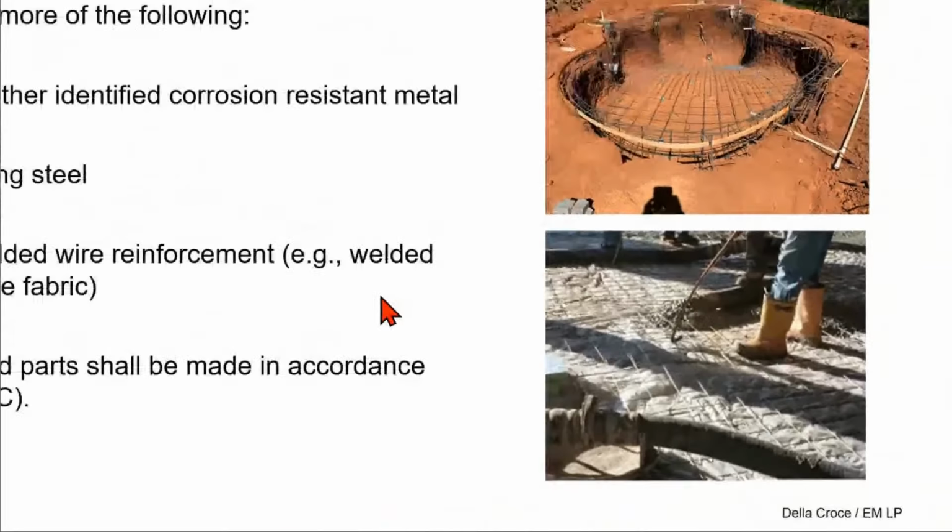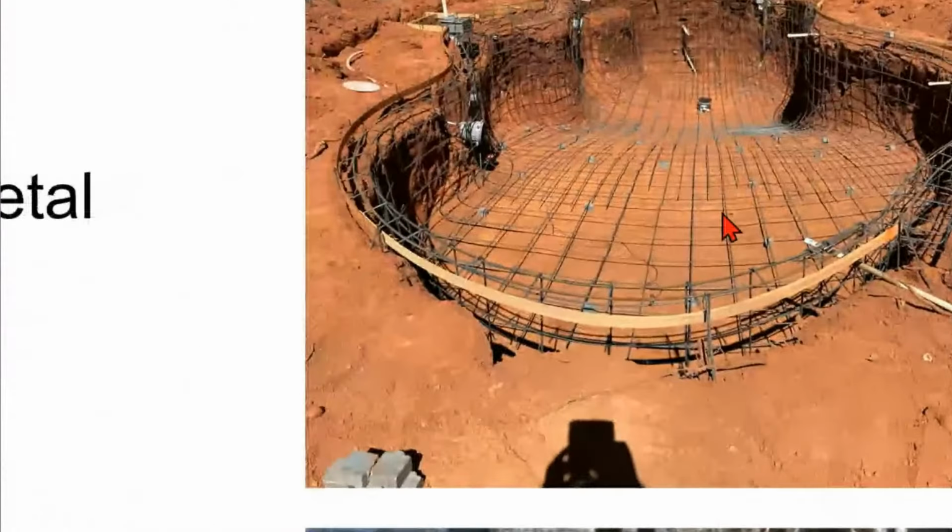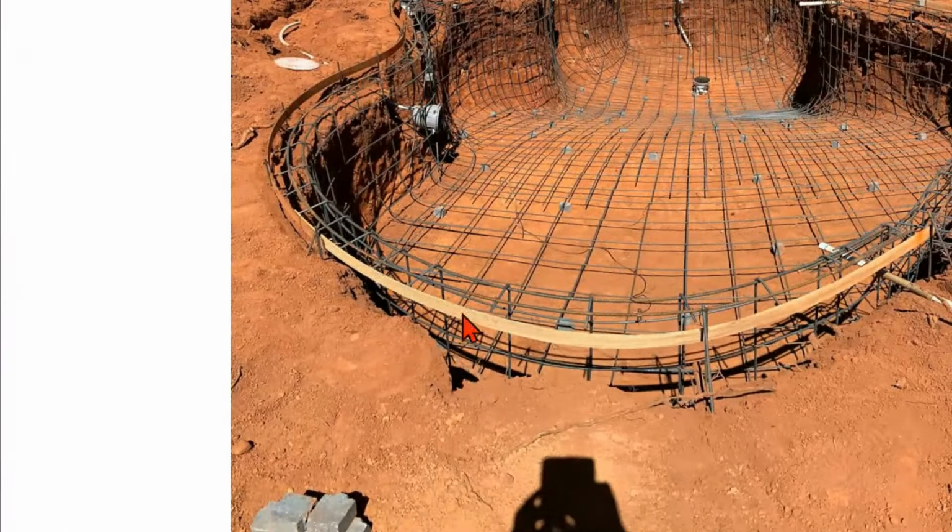Okay, got that. And of course, this one, that is all of your rebar. So that is your conductive pool shell laying all in. I do see some bonding being done through here. Looks like it's a different bonding.